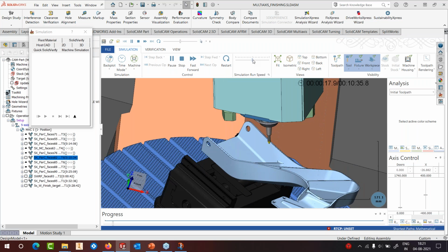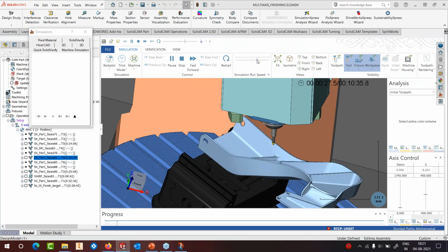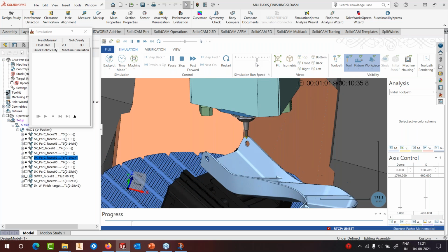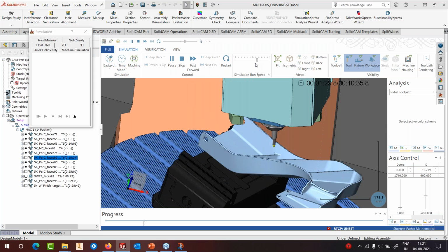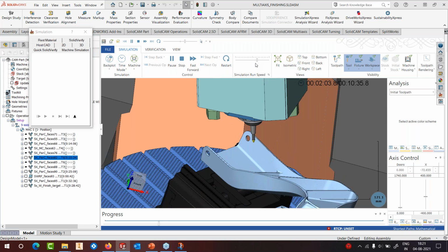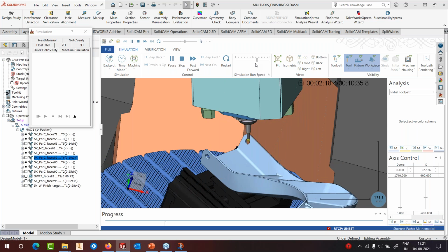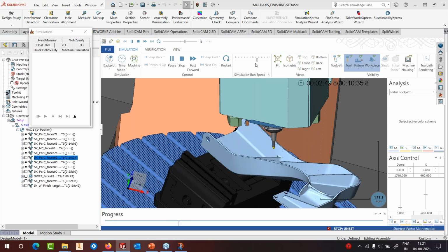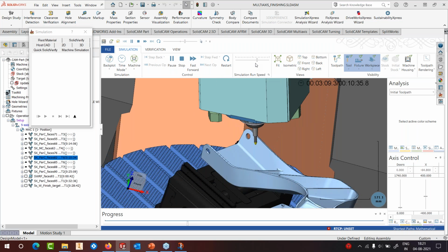Okay, so that's how it's going to machine. You will always see the large radius of R250 that is in contact. So whatever 1.5 millimeter I've used here will help me generate that scallop of 1 or 2 microns on this particular surface. So you can actually use generic to machine any kind of part using circle end mills.